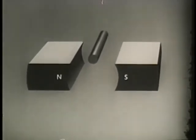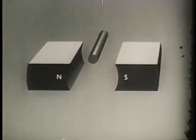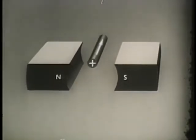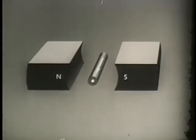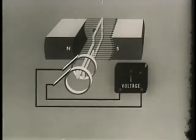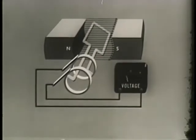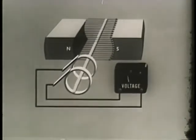To illustrate the direction of current flow, the conventional symbols will be used. Current flowing in a conductor away from us is represented by a cross, toward us by a dot. However, moving a conductor in and out of the field in this straight reciprocal fashion is awkward and impractical. A simple generator of EMF can also be made by rotating a single turn coil within a stationary magnetic field of two magnets with opposite polarity.